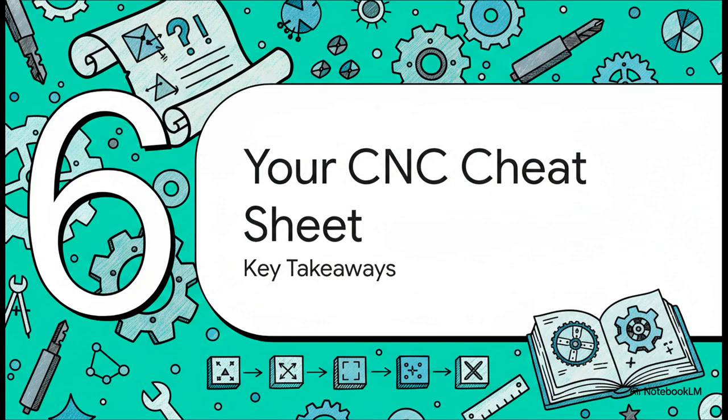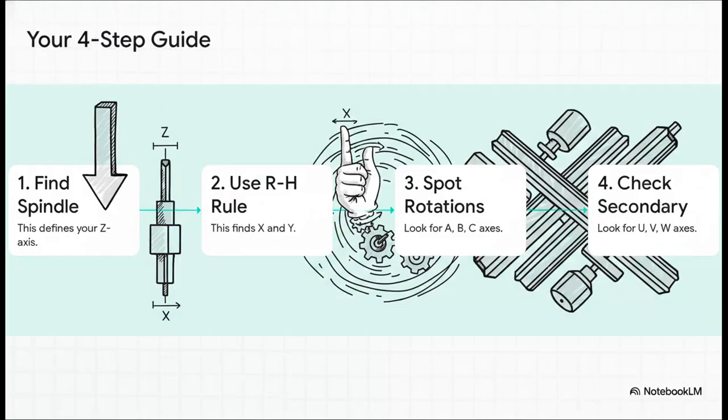Okay, I know that was a lot of information, so let's boil it all down into a simple, step-by-step process you can use anytime you walk up to a new CNC machine. This is your cheat sheet. Here it is, just a 4-step process. Number 1, always find the main spindle first. That defines your Z-axis. Number 2, use your right hand to instantly figure out X and Y. Number 3, look for any tilting or rotating parts to identify A, B, or C. And finally, number 4, on those really complex machines, check for any secondary slides or spindles, and those are going to be your U, V, or W.